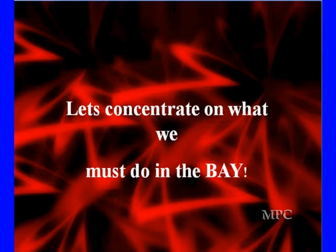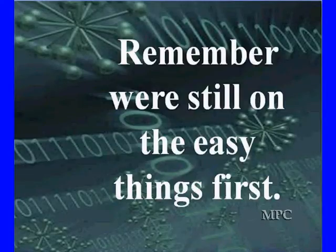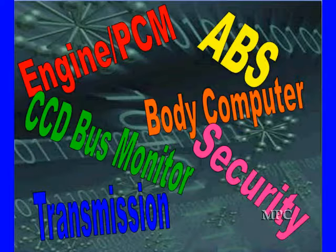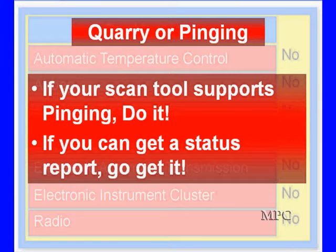So let's concentrate on what we've got to do in the service bay to start diagnosing cars and start thinking about diagnostics. Remember, we're still on the easy things first. Getting back to your scan tool, which data are you having trouble with? Go in and see if you can access each one of these. Can you see the body computer, security, transmission, ABS, engine, PCM? Try to communicate with each module.